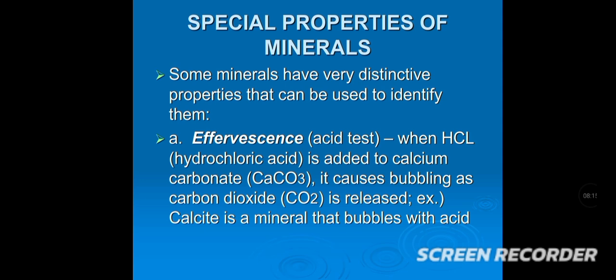Because in the field or on site, calcite is rhombohedral in shape and white in color, but the same is true of feldspar. It also sometimes shows white color and has a parallelogram shape. So to differentiate between feldspar and calcite, effervescence will be our identifying property.